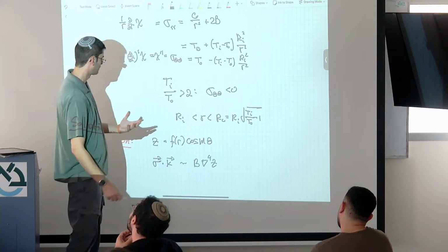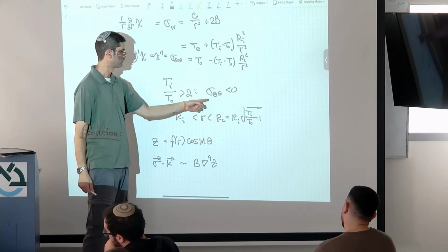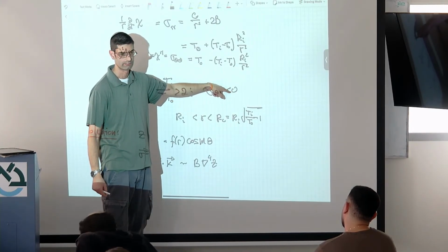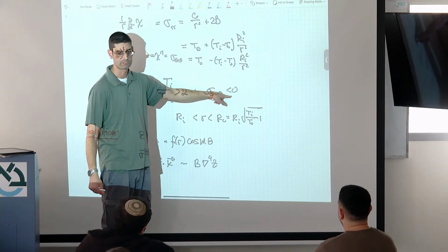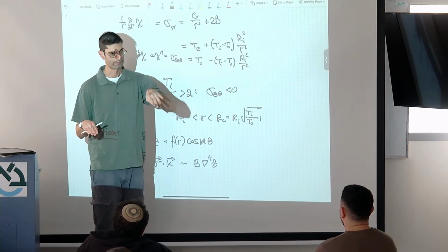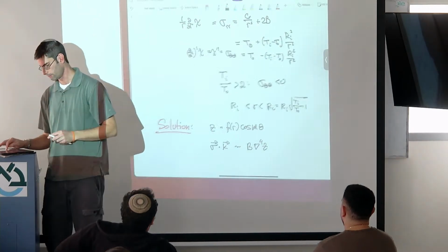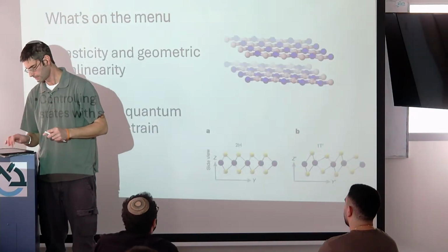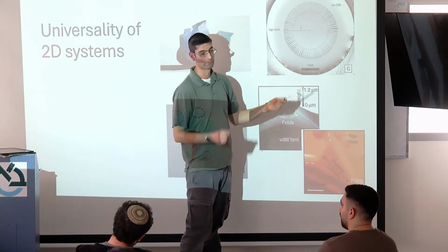The point is that what I'm doing is I'm relieving this stress. I create an area where sigma theta theta is actually exactly 0, or asymptotically 0. So I find a solution where instead of it being smaller than 0 everywhere, I just put sigma theta theta equals 0. And the way I make the hoop stress 0 is by creating these wrinkles. And this is exactly what I started by showing you, if you remember, last class. Okay? This is actually a paper where this problem is solved.